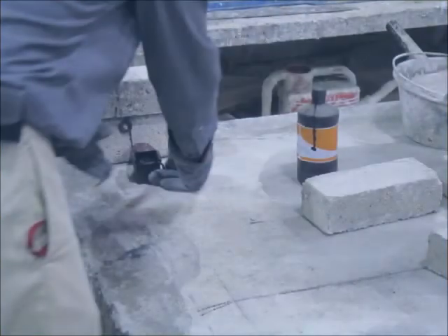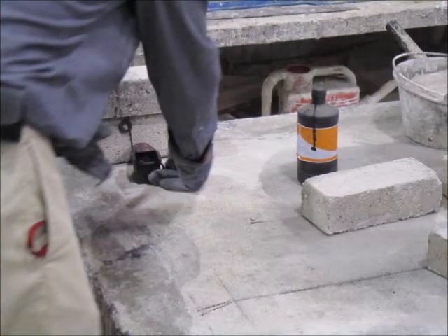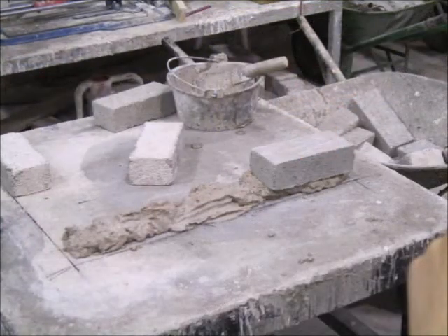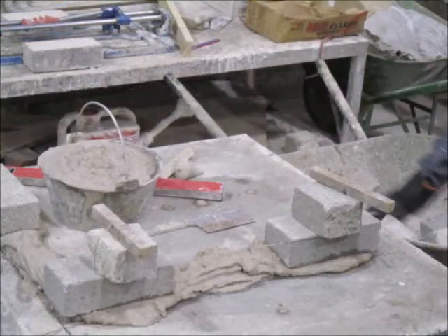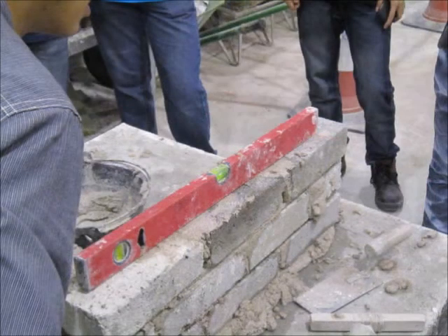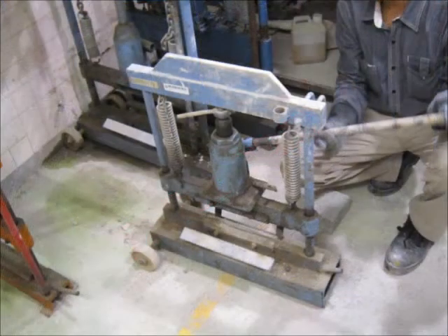In brickwork and plastering training, we were required to lay a brick wall. When laying bricks, we need to mark the position first. Second, we place some cement mortar on the position and then lay the brick. Before laying the remaining bricks, it is essential to measure the leveling. Moreover, we can use cutting machines to cut the brick into a suitable shape.